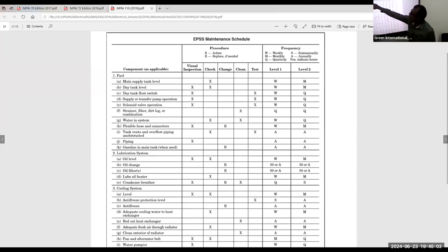So we have visual inspection and testing frequency. We can find all the answers from the word itself. For example, we have one question: we need to find the testing frequency for a lead acid battery. The keyword is lead acid, so we can use NFPA 110 or 111, because batteries are related to these. First priority, we refer to these two documents.